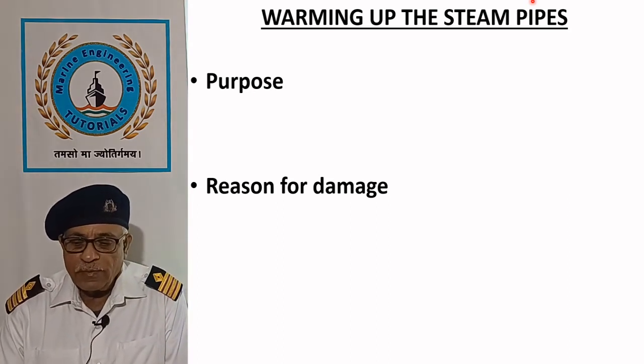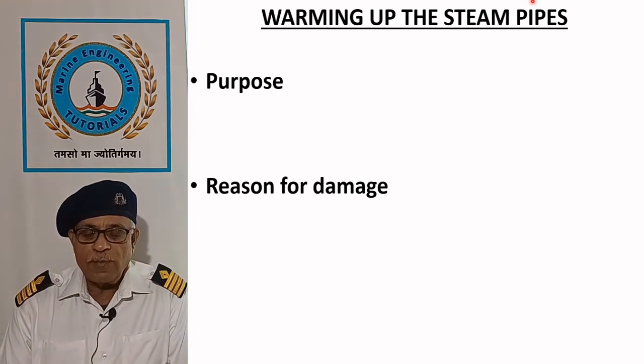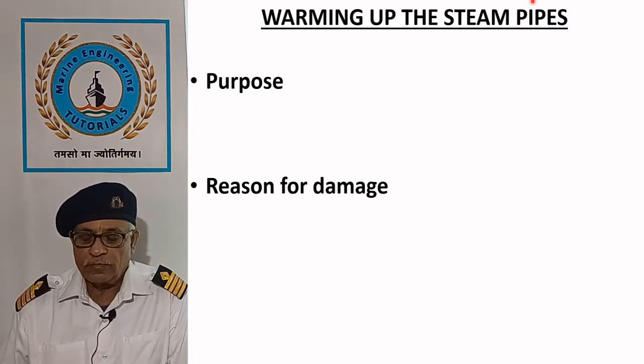Severe damage can be caused by water hammer when steam is admitted to pipes containing water, especially when the pipe has a slight inclination from the horizontal, which may allow the water to have a large free surface area.